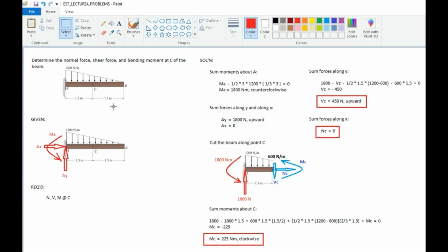So, you have a 3 meter cantilever beam subject to a triangular load. Then point C is at the middle. Okay, so, what will you do first? First, you show the reactions at the support. Okay, so we have 3. So, along X, along Y, and the moment. Okay. Now, what is required of the problem is the normal, shear, and moment at C.